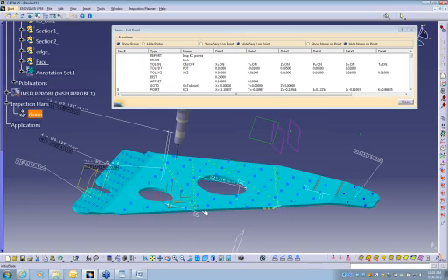So is it done a lot? Probably not as much as a DCC CMM, but it is a good way to create your inspection points on the model, and that way you don't need to worry about a translation. Because going into these products like VeriSurf or Spatial Analyzer, even though they say they have CATIA read, it's still considered a translation by the OEMs. That is not a pure V5 inspection. They reverse engineered the CATIA file, and they're able to open it up, and it is considered a translation.